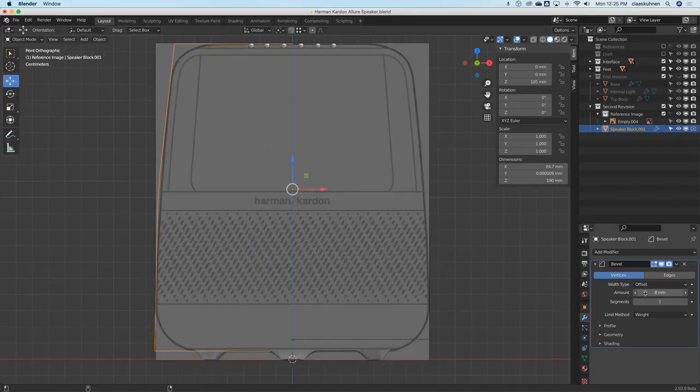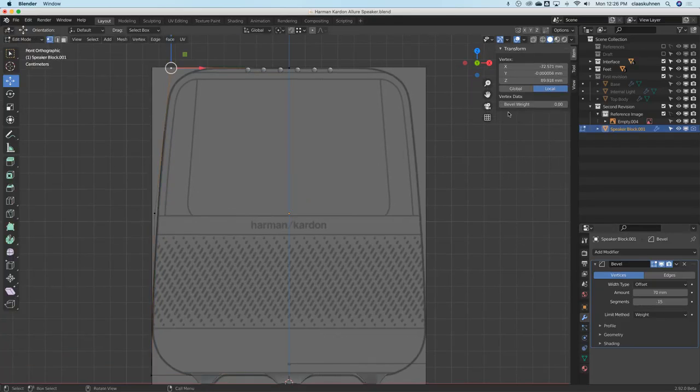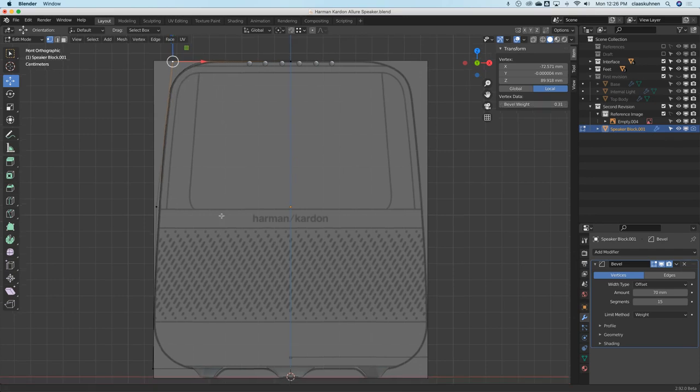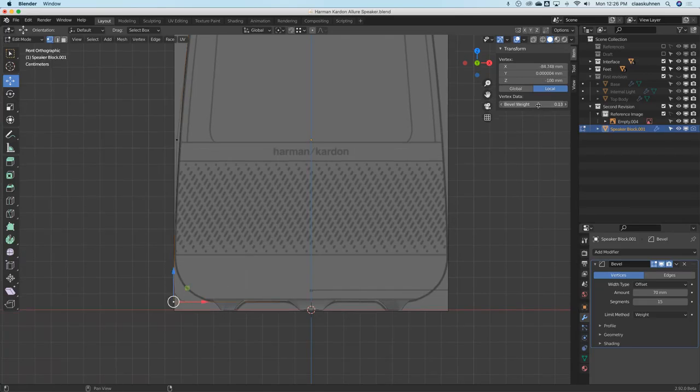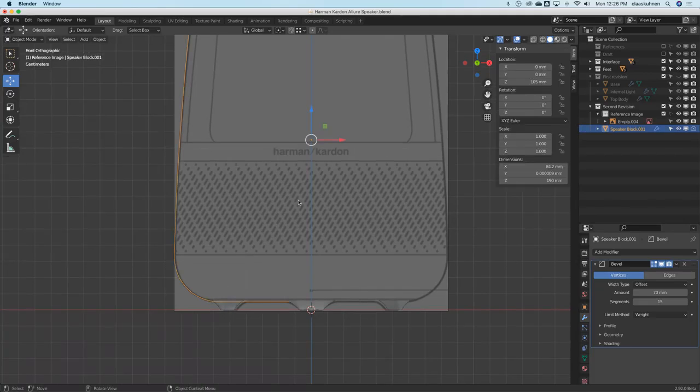So when I lower this there, we can see, yeah, there it is roughly, and I think it's plus minus there, 70. Yeah, maybe 15. Yeah, that looks actually pretty good. And then we can go to here, and now there we just have to be careful that we can't go 100% because then we start cutting into the previous fillet, maybe a little bit smaller. So we work just with the percentage.